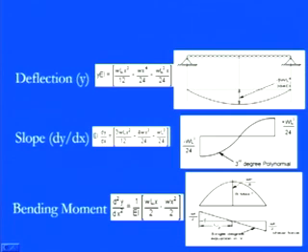Now with that bending moment diagram you can again visualize the shear forces, which in this condition are positive in this region and negative in the other region on the right hand side. So we have WL by 2 in the positive region and minus WL by 2 in the other region. So it is passing through those values. Again we have a very clear reason that these equations are almost equal to those conditions.